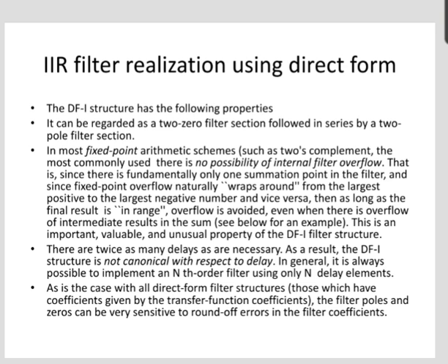There are twice as many delays as are necessary. As a result, this structure is not canonical with respect to delay. In general, it is always possible to implement an nth order filter using only n delay elements.